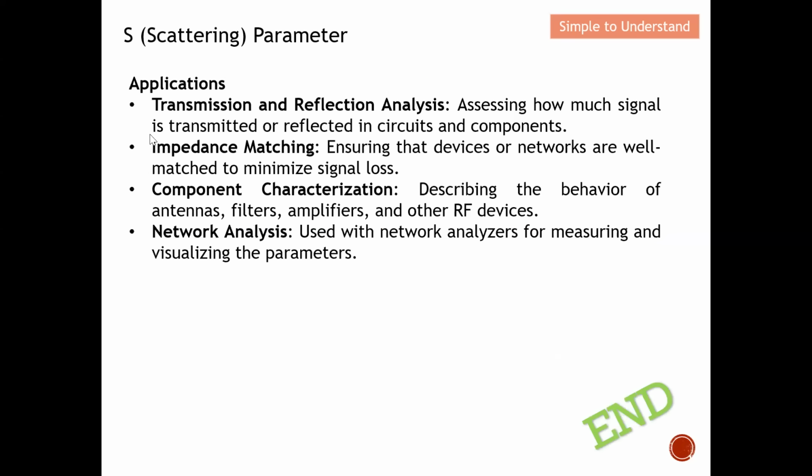Let's do a quick conclusion on the applications of S parameters. With transmission and reflection coefficients, you can do some form of analysis. You can assess how much signal is transmitted or reflected in a circuit and also in a component. For example, you can measure the S parameters of the whole circuit or of a component, such as a filter, an antenna, or an amplifier. So you can measure the transmission and the reflection, and analyze how much you want to transmit and how much you want to reflect based on S11 and S21.